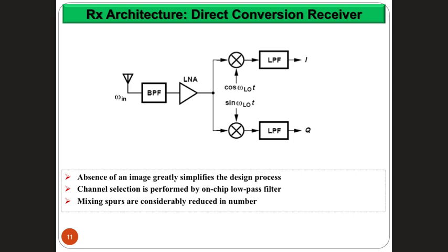So why do we have a sine and a cosine here? Exactly, because even if you bring the signal directly at once to 0, if it's not symmetric, you will end up with self-image. So that's why for direct conversion, you have always to use the quadrature, the two components, sine and cosine. Okay.